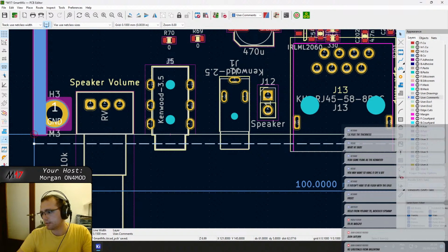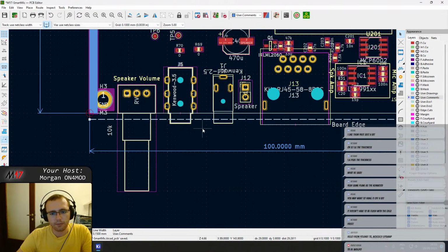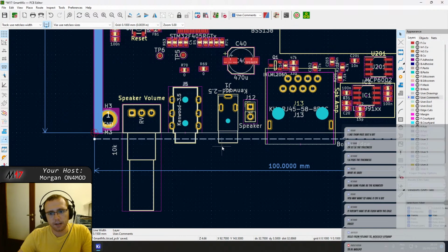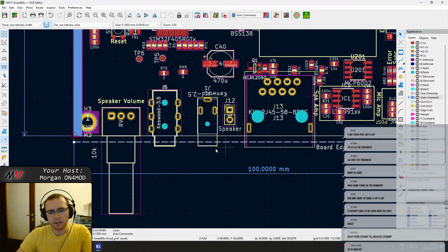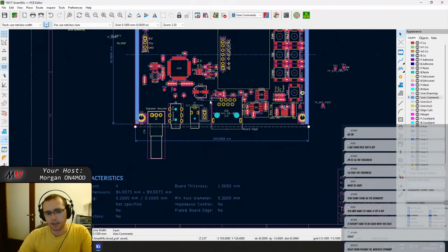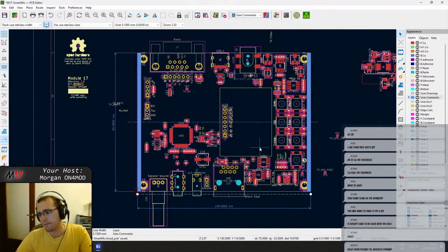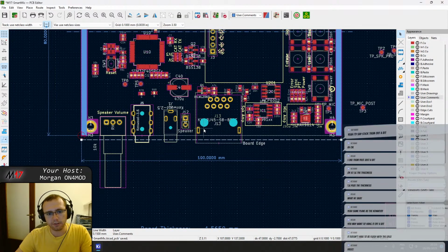Thickness of what? I think 1.6 is the thickness of the PCB, and in my reasoning, the PCB is against the board. So maybe we can give it a bit of clearance because it's not gonna be straight on, but I would prefer them not to go further than the face, so maybe 1.6 is good.